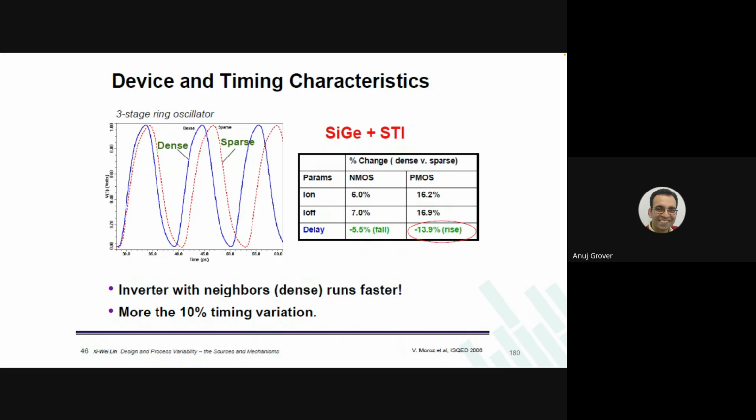We'll probably talk about it later. You might have already seen that session, where I was talking about a failure that we observed in a particular memory because the word line was running in metal 3 and the precharge was drawn in metal 2. Metal 3 and metal 2 are two different process steps altogether.